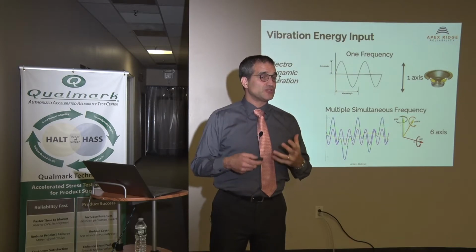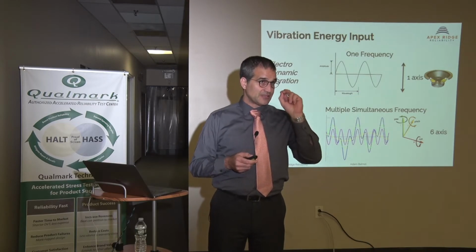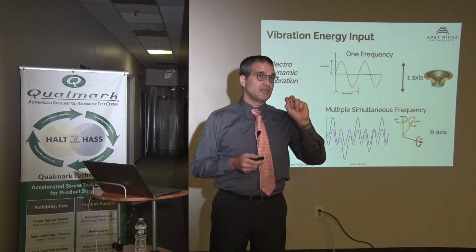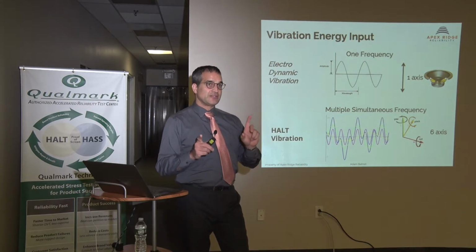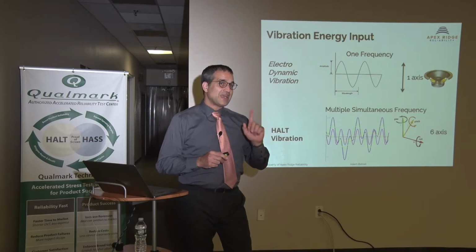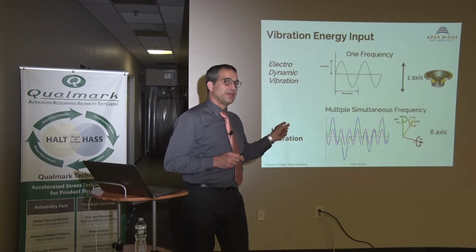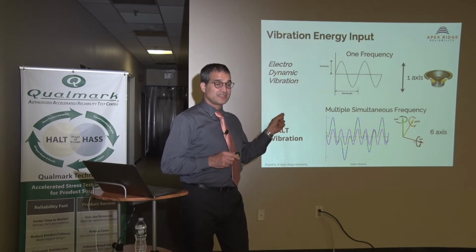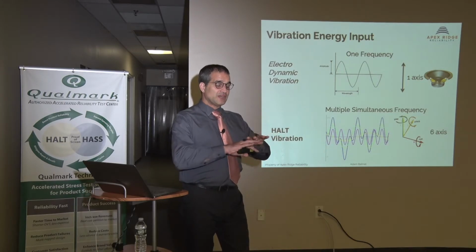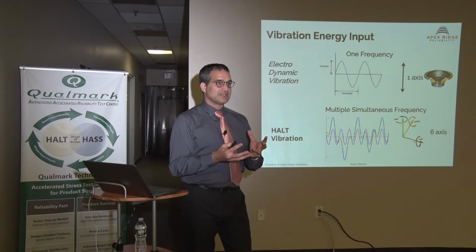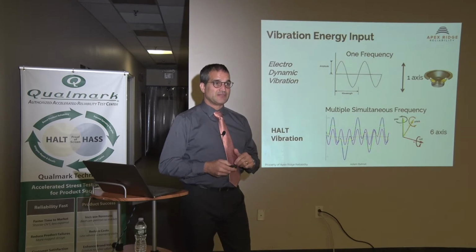But if we're looking to create failures as quickly as possible, and not looking for a specific relationship between a single frequency or direction of a stress, you want to get as much in there as possible. So it will do it in all three axes, linearly and rotationally at the same time. And this is where an amazing part of the technology comes into play with the table. Broadband frequency. It does multiple frequencies at the same time in all 6 axes. And that's where the technology of not just vibrating it by putting something on that's oscillating, and having that energy transformed through the table, makes a big difference.